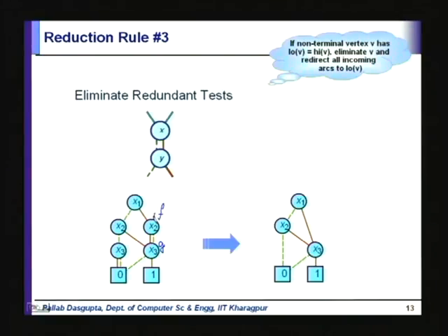It represents f is equal to x2 times g plus x2 bar times g, and what happens? You take g common, x2 plus x2 bar, so this is effectively equal to g itself, right.